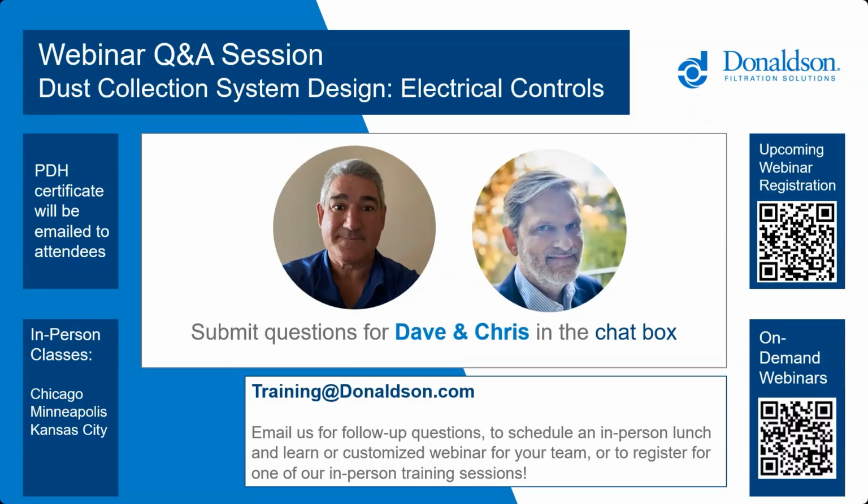You do need to be able to produce a KST value, which is an expansion rate of the dust, which is what's achieved by the testing of the dust. But if there's information on the internet that you can say this dust will not exceed a certain KST, then you can use that value. I would say it's all dependent on the authority having jurisdiction, if they're going to require it for stability and security. So consult your AHJ just to make sure.